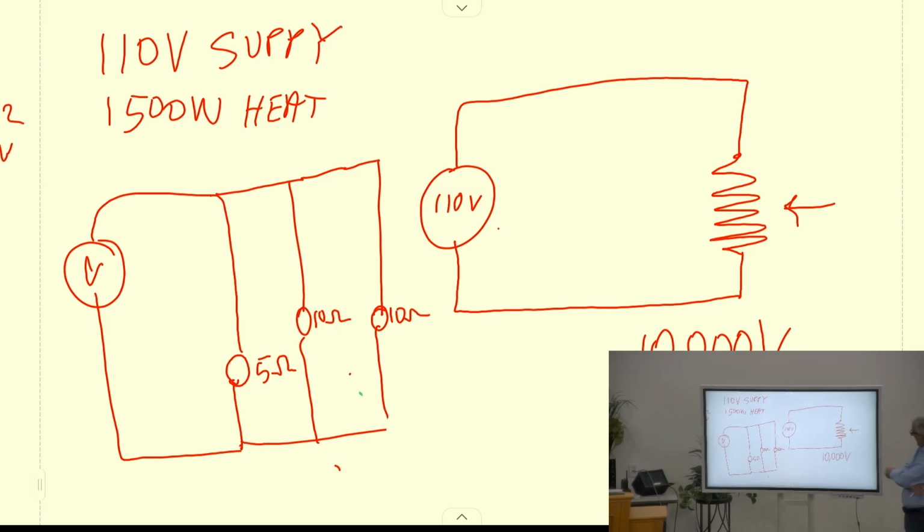But back to voltage and transformers: if you're transmitting power a long distance and you don't want to spend a fortune on the size of the conductor, and let's say I want to transfer 10,000 watts of power, well, if I have a 10,000 volt source, then I only need a 1 amp wire for 10,000 watts.